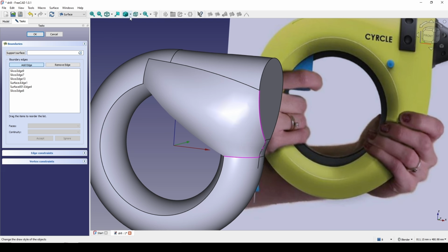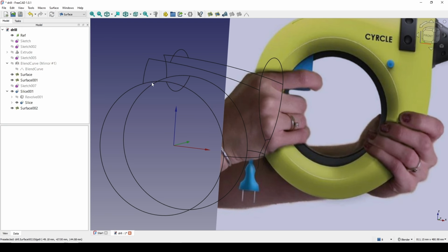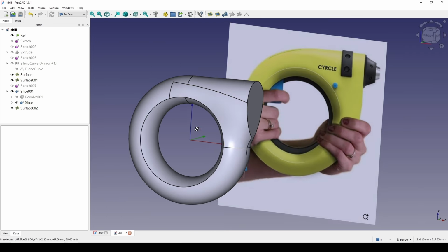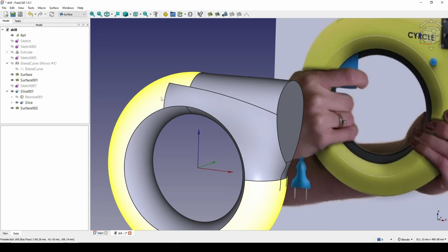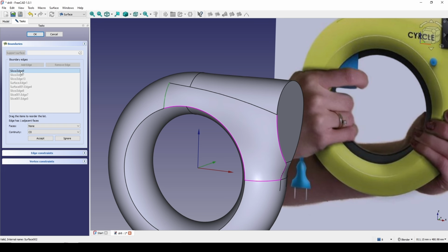And let's show the wireframe. This one and this one, and click OK. And let's show the flat line. Now I want to set the continuity in here, the first edge. So I double click on the surface, go to the first edge, double click on it, which is this one. Go to the face and set the G1 continuity. Set.